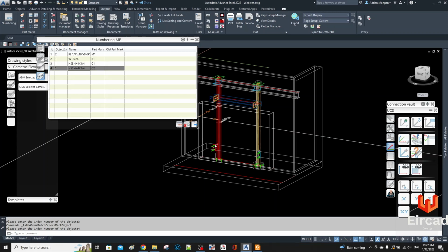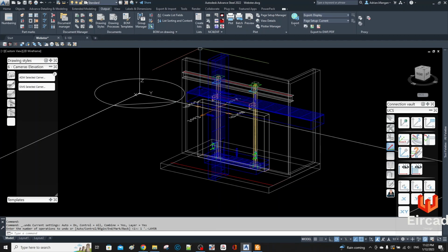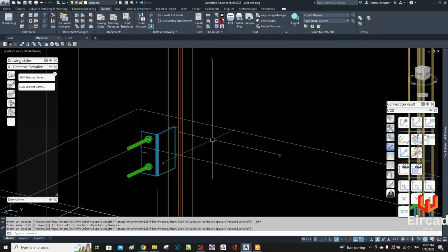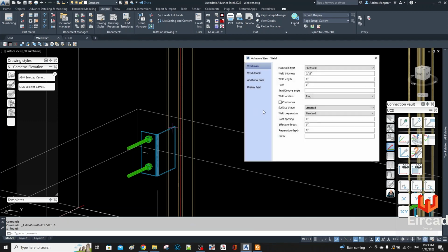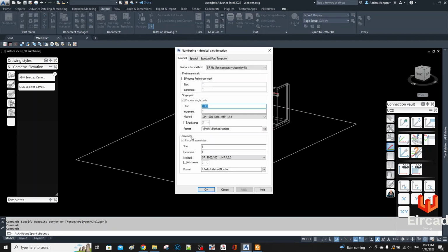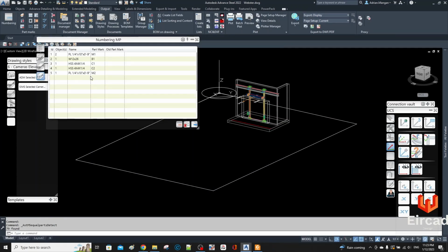So I messed up there, right? So this is still a field weld, so I don't want to do that. So let's back out of this. Turn the cameras back on, so now I know the numbering has undone. Also, you'll see it down here if you read down here. So cameras, okay, let's go back in here, double click on this, site weld, okay. Let's try again, see what happens. Probably the most used button is undo.